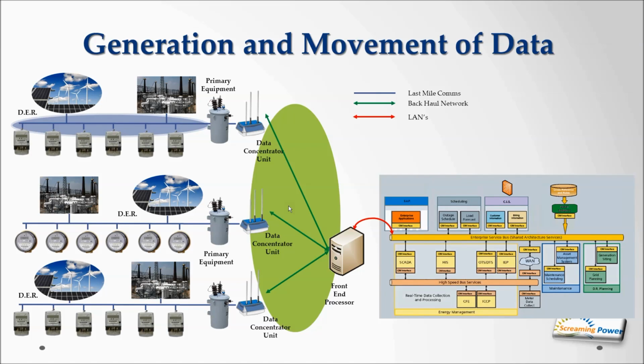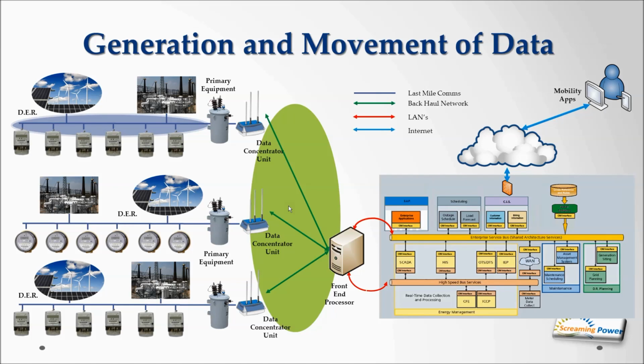The first LAN is the enterprise service bus, which is a slow speed bus, and we have low data rates of typically minutes or hours characterized on that bus. And we also have a high-speed bus, which is the operations, and here we need the data to be fed into the enterprise or into the operations side every, let's say, sub 1 minute, 30 seconds, 15 seconds, whatever.